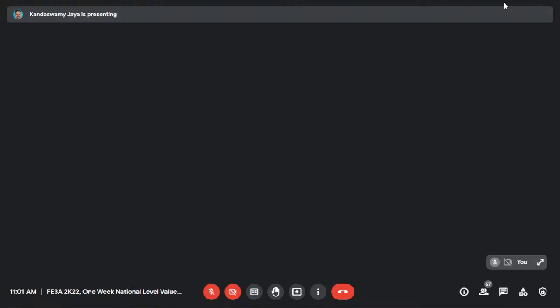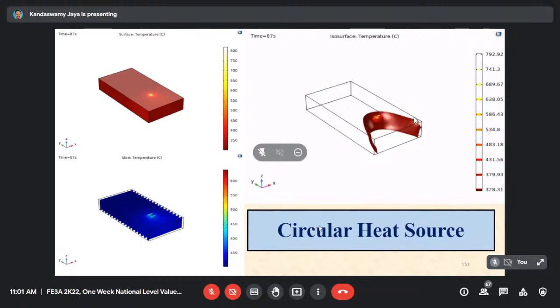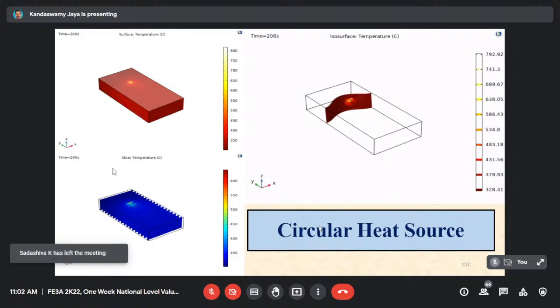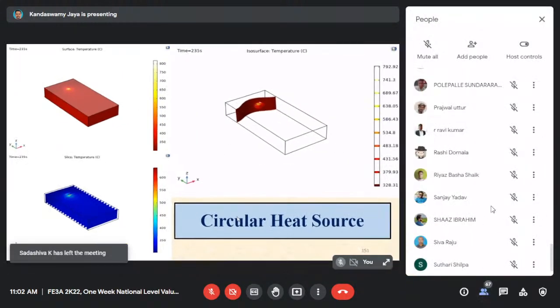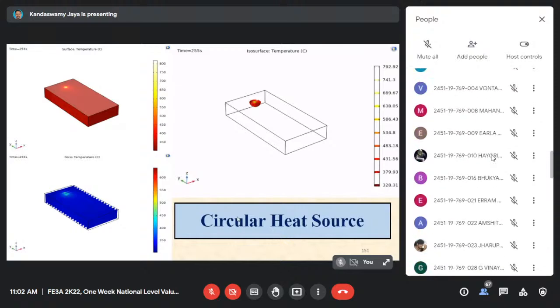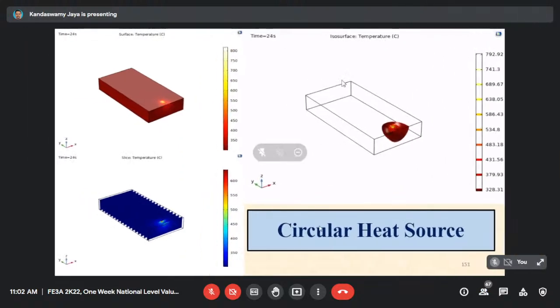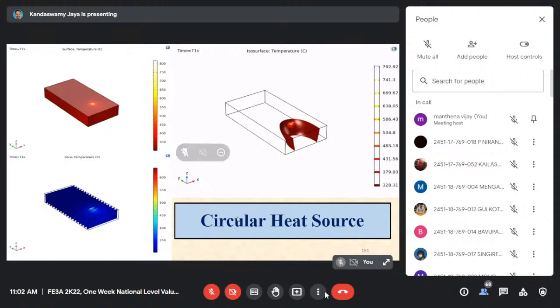It moves. How my temperature will flow, you are seeing on the right hand side. How the temperature dissipates. So you could see it frame wise, slice wise, on the surface, in cross section, different cross sections you can view. This is the beauty of any FE software. This you can't see while doing welding. And these temperatures will match very nicely with my experimental temperatures. Whereas that you won't get in the previous case, what you have seen.